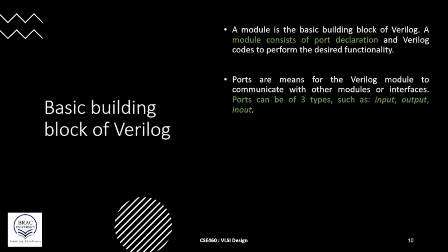For the remaining slides of this presentation, I'd like to introduce you to the basic structures of Verilog. The basic building blocks of Verilog are the modules and the ports associated with them. On the surface level, the Verilog module can be thought of as a black box that encapsulates the desired logic operations. Ports are basically the means for communicating with other modules.